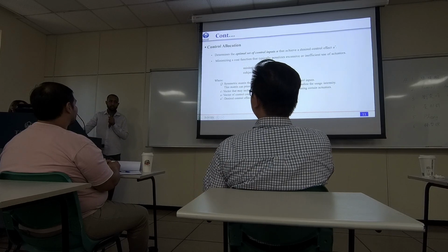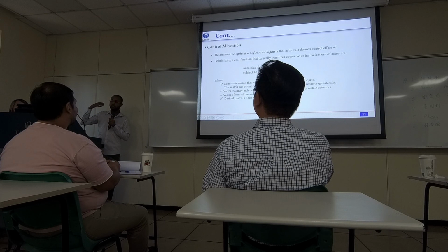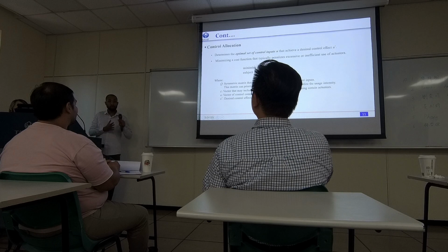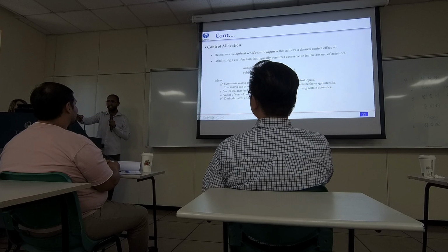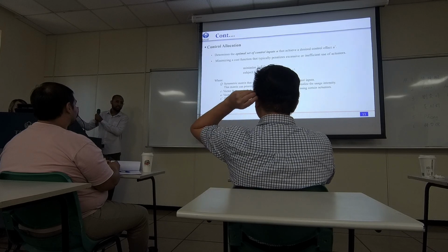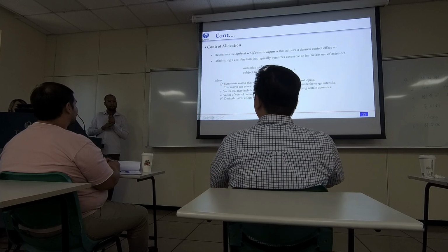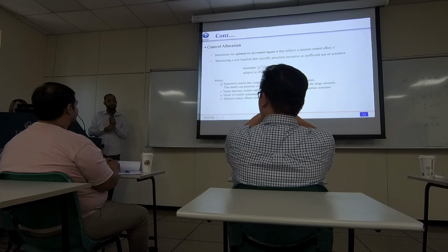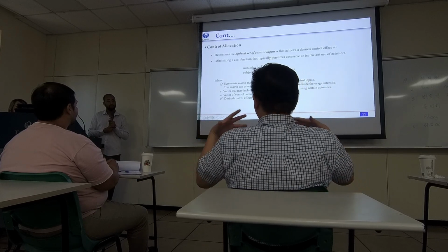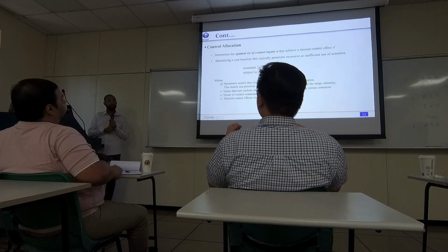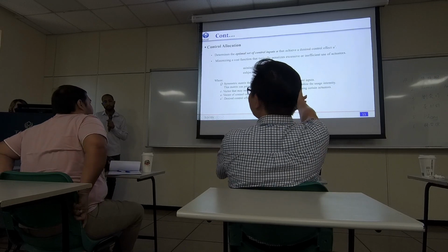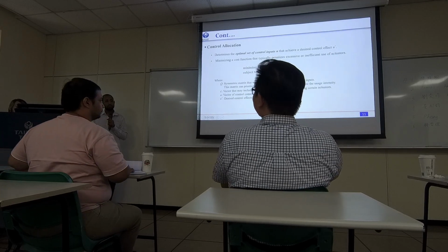What we need is control allocation. The previous stage by itself can control the vehicle effectively. But what we need here is to allocate the control, because we have two things to actuate: the steering and the differential braking. So whenever you need to do something with the vehicle, you need a second part, I think. But what I'm saying is, in the usual cases, when you are driving smoothly on the road, you don't need to solve optimization, just drive.